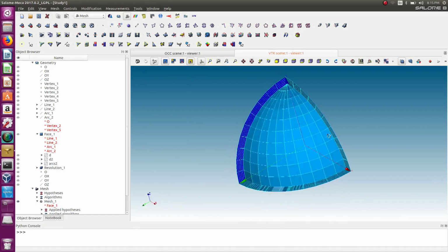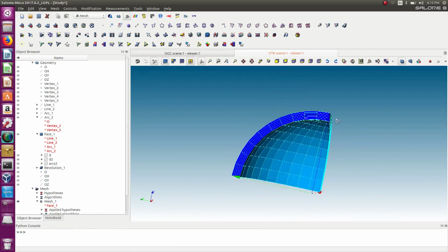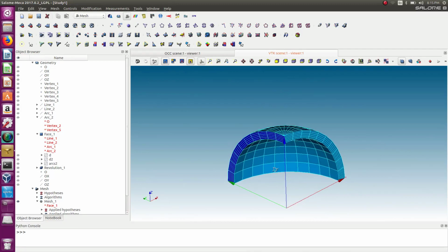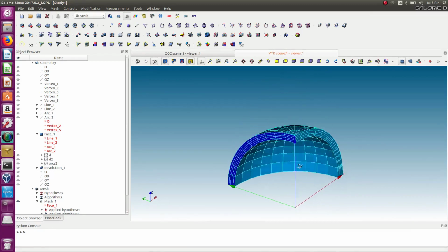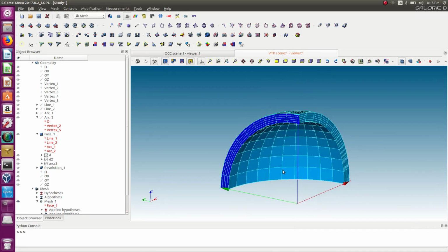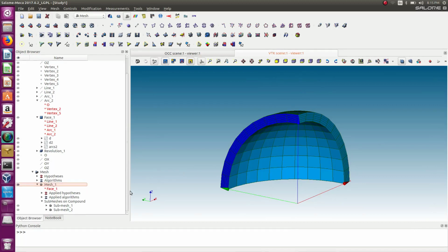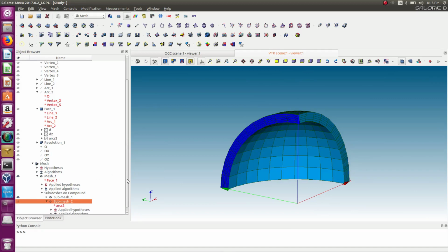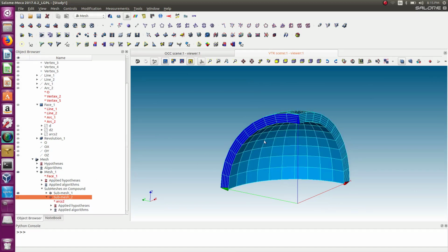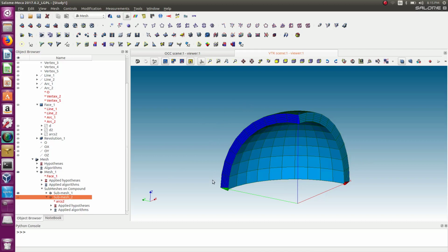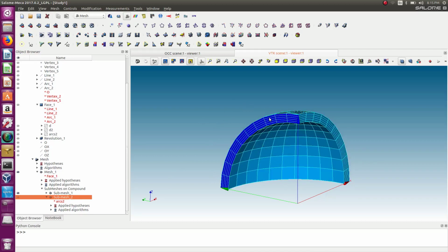Okay, and now I got my mesh. So now unfortunately it's not totally finished because I need to create the groups for the mesh. So that's kind of the boring part, but you will learn a few things also how to do that, because I extruded the mesh from this face, but the solid that I created before is not really associated to that anymore, because I didn't mesh from this solid directly.